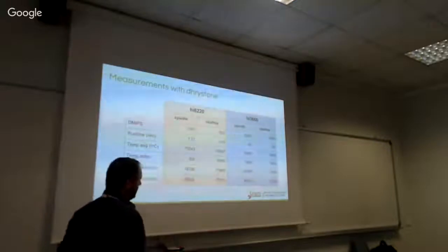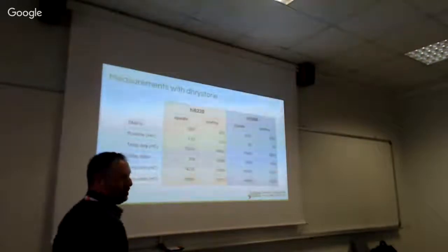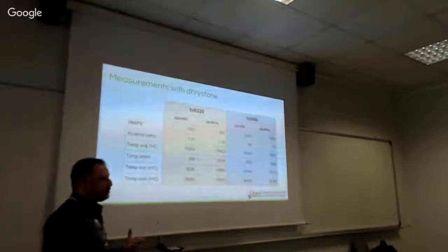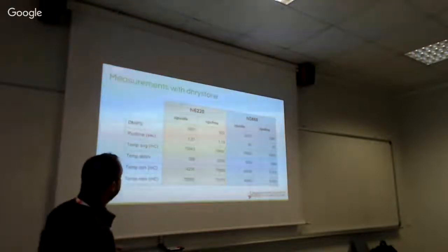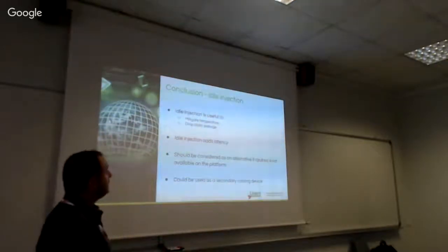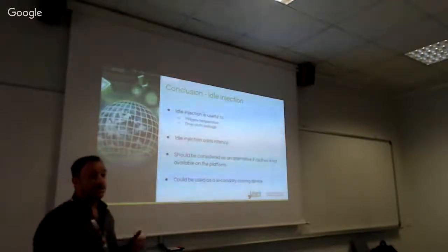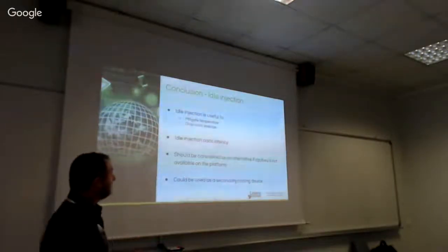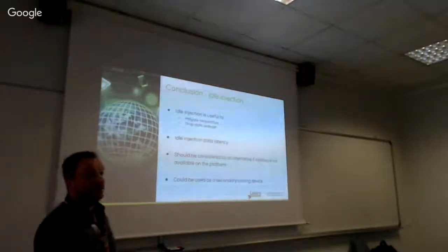That's expected. We are adding idle duration, of course, it is longer time. So the idle injection is interesting to mitigate temperature, to drop the static leakage, but the drawback is it adds latency to the system. So we should consider this as an alternative for cpufreq if cpufreq is not available.